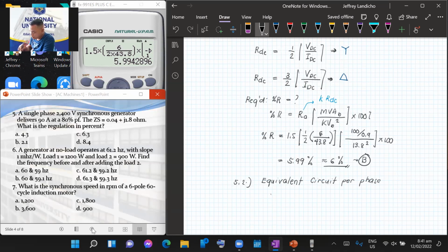Let's say we take line A. It is Y connected, so connected to ground or to the neutral, then there should be its corresponding synchronous impedance, as it is called. That should be its armature resistance and synchronous reactance. So this would be our terminal A. So that is where we connect the load.